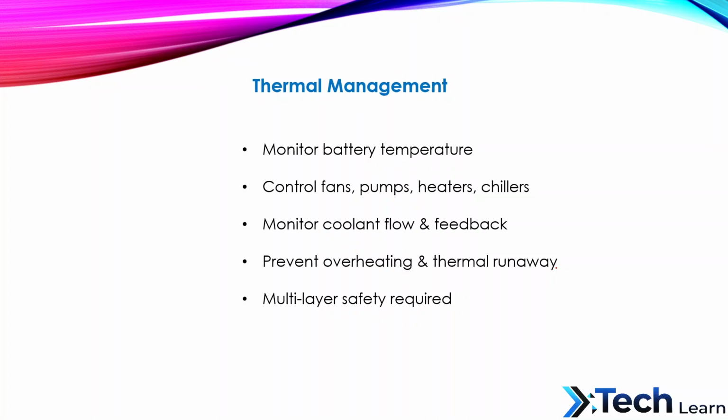Now we are going to move into thermal management, where in a large format battery system, thermal management is critical, as battery temperature affects performance, aging, and safety. So the BMS monitors battery temperature continuously. It may also monitor coolant inlet and outlet temperature.